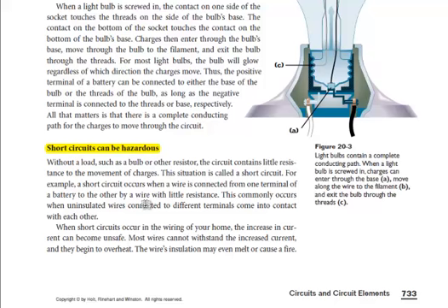For the same potential difference, but with resistance dropping, usually substantially, current rises substantially. And that increase in current can be unsafe. Remember, lots of current means lots of heat production, and that can cause fires. Also, lots of current is what electrocutes you. So suddenly we have a situation that may take it from a safe device to one that's life-threatening in a variety of ways. This is where our fuses and circuit breakers come in.